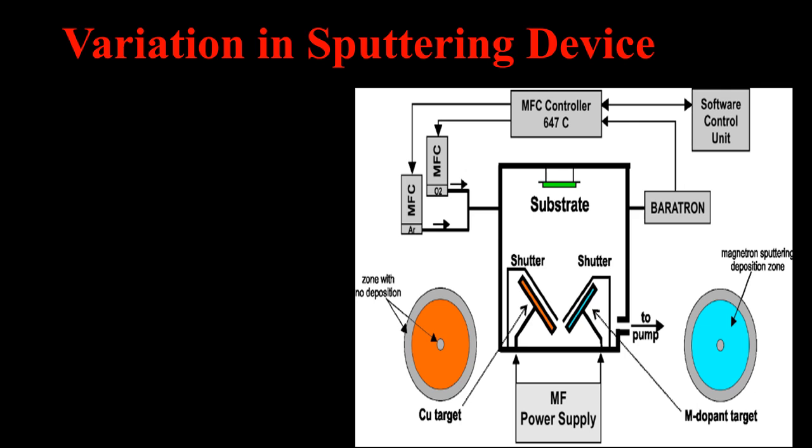Now at the same time, if you want to deposit complex source materials as one thin film, the shutter is removed from both or many of the source materials, and they are targeted by the inert gases like here and also here, and they get evaporated and deposited onto a substrate.